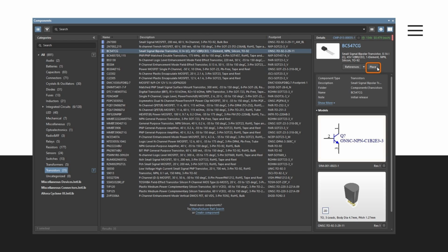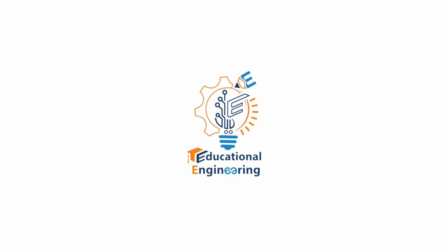Lastly, click, hold, and drag. Click and drag the component from the grid region of the panel onto a schematic sheet. This mode requires the cursor is held down, the component is placed when the cursor is released. Using this technique, only one component is placed. After placing the component, you are free to select another component or another command.